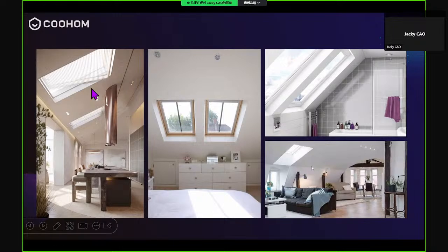Actually, for the windows, you can also draw, and even if you want, you can try to dig the hole by using the 3D subtract, right? And then you just need to draw the two columns and then cut. Yeah. Sometimes if you want, you can draw the rectangle and push and pull and then delete the surface. It's still the same logic, right?